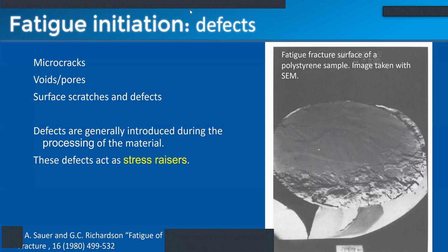So to get good fatigue testing data takes a long time, takes a lot of samples, because you have to test all the way to failure of the device, number one, and two, because the defects or the cracks that cause failure can be different from device to device.